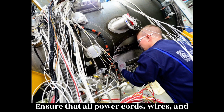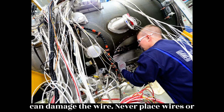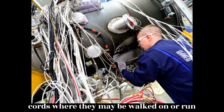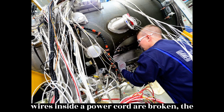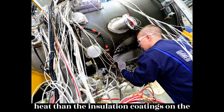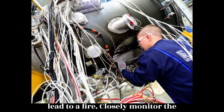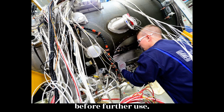Ensure that all power cords, wires, and lines are free of kinks and bends that can damage the wire. Never place wires or cords where they may be walked on or run over by other equipment. When several wires inside a power cord are broken, the current passing through the remaining wires increases. This generates more heat than the insulation coatings on the wire are designed to withstand and can lead to a fire. Closely monitor the condition of electrical equipment. Repair or replace damaged equipment before further use.